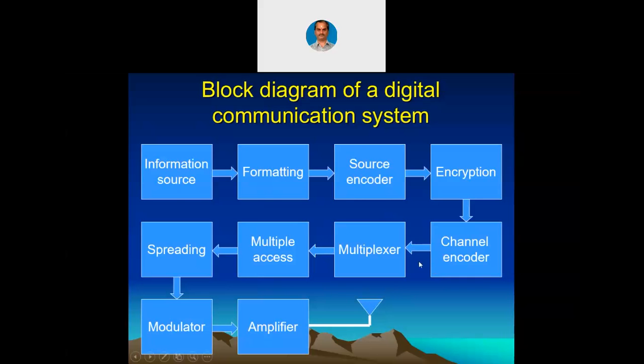Multiplexing is only for a single information transmission, whether audio and video, or audio, video, text, music, data, voice. Multiplexing is to pack a large amount of different types of information into a single channel, whereas multiple access is that a particular channel can be accessed by multiple users.